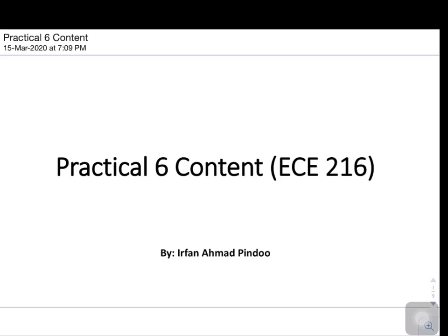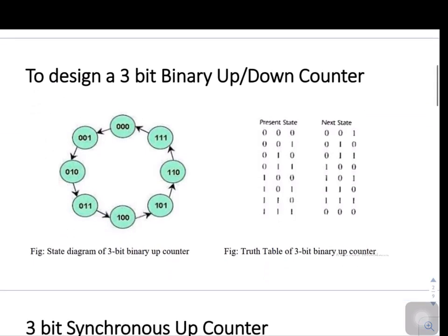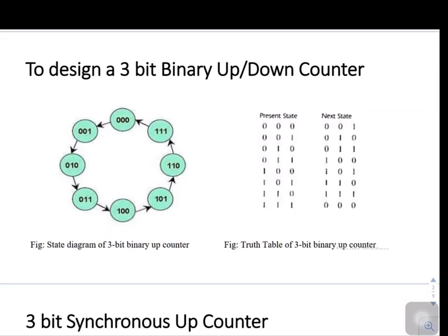So if you look at your lab manuals, practical 6 deals with the designing of a counter, and the counter that we are designing in this particular practical is a synchronous one. That means the clock pulse would be given to all the counters at a time.